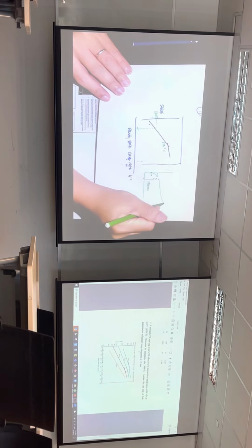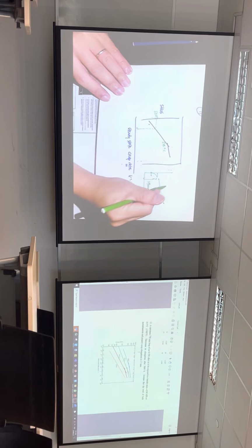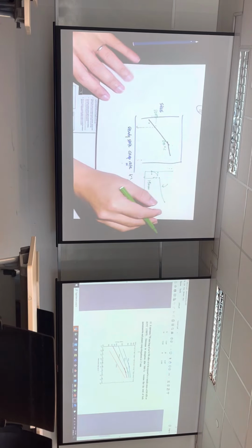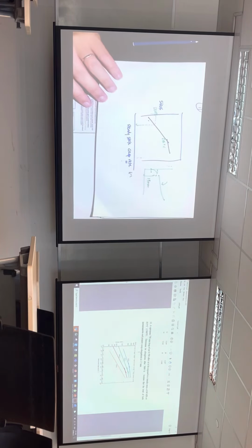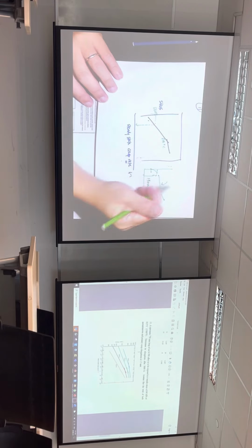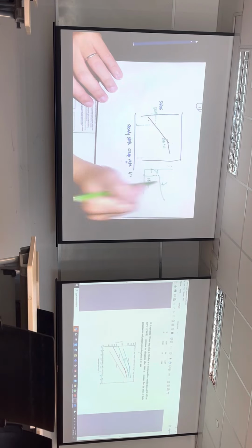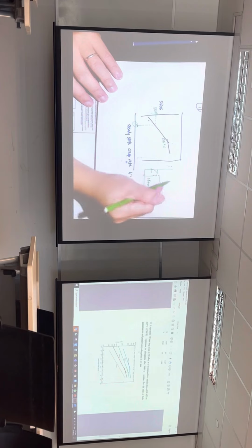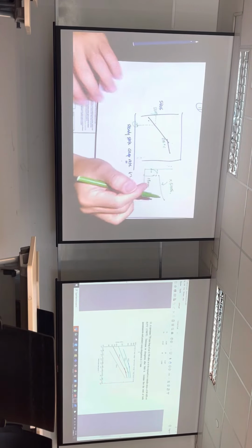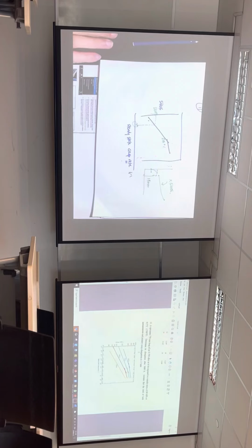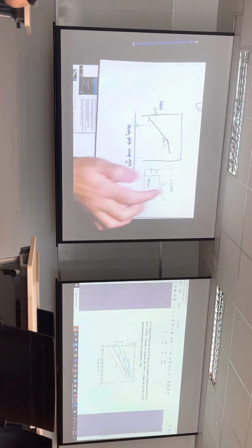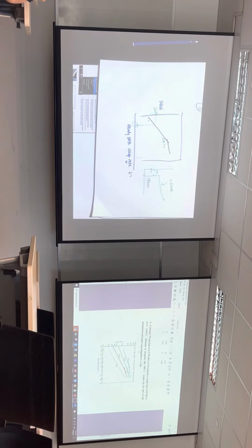And then for the steady state one, you can find the creep by using the creep rate based on here times 5,000 hours. Based on the creep rate, you can actually find the extension. Then the total extension will be this 1.5 mm plus this value.